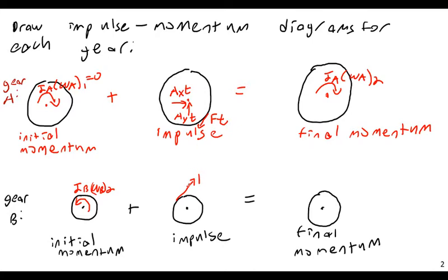It's the same force here, but do keep in mind the directions of these. They need to be equal and opposite. As long as we still believe in the laws of dynamics, as long as we still fear Newton's ghost, whenever we draw a set of forces, we need to make sure to draw them in equal and opposite pairs. I don't know why you would fear Newton's ghost, but I suppose you could. Anyway, the rotational impulse here will simply be M times t. That is the moment that will be applied to this thing.